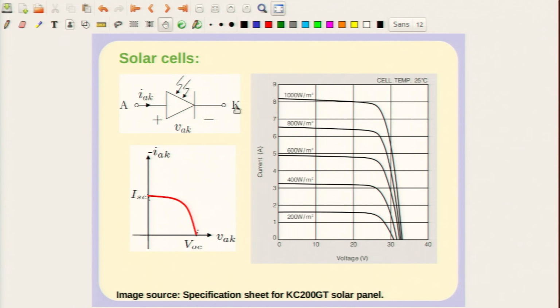So, if the diode is just connected to a resistance, then wherever the IV characteristic of the resistance, which is a straight line, intersects this curve, is the point at which you will operate, and that much power can actually be delivered to that resistance. So, this is what a solar cell does, it converts the light energy into electrical form.